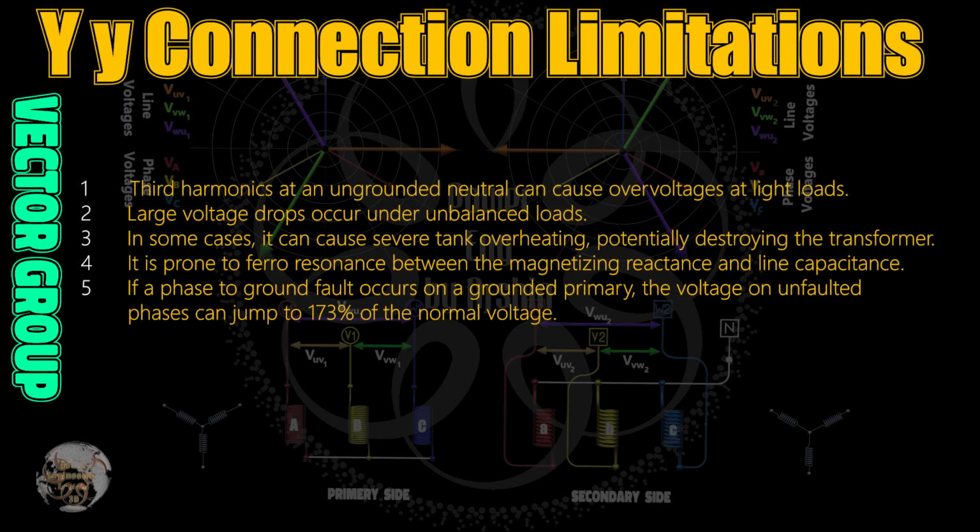You must be aware of the limitations of the YY connection. 1. Third harmonics at an ungrounded neutral can cause overvoltages at light loads. 2. Large voltage drops occur under unbalanced loads. 3. In some cases, it can cause severe tank overheating, potentially destroying the transformer.